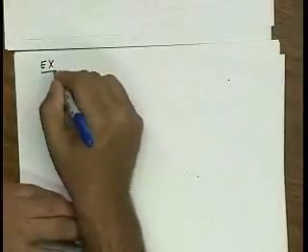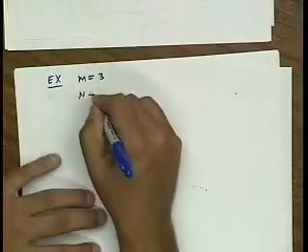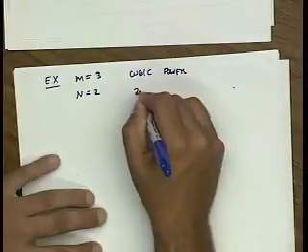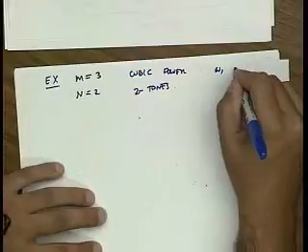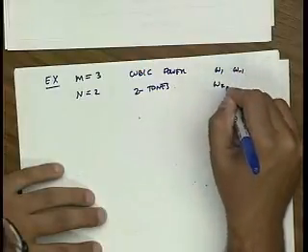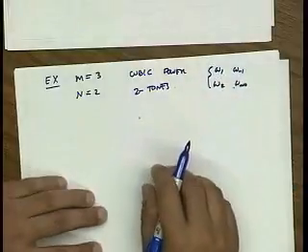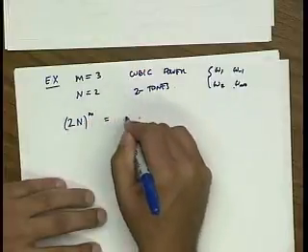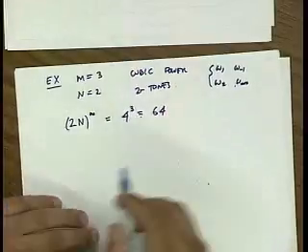Let's take an example to bring this home a little bit. Let me take something simple that we've dealt with: a cubic nonlinearity and two tones. So this is cubic power, two tones. My frequencies are omega 1, omega minus 1, and omega 2, omega minus 2, which of course is just minus omega 2. So how many terms do I have? I have 2n to the m terms. That's 4 to the third power, or 64 terms.